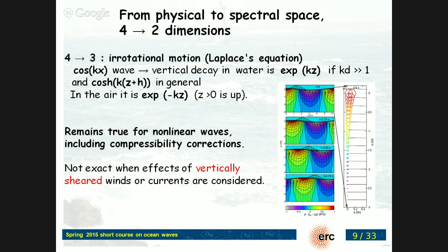Right. So kD larger than pi, half wavelength, is deep water. And actually, if you're looking at motion in the air, it's exponential up, and so the particle in the air also oscillates with the waves, and that decays exponentially. So that's true even for nonlinear waves. So nonlinear waves have the same properties.